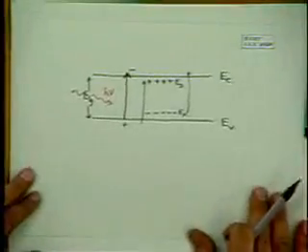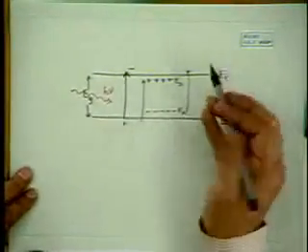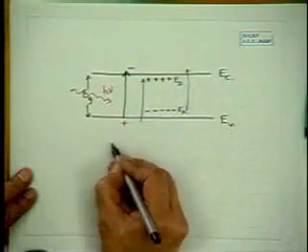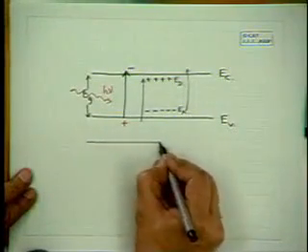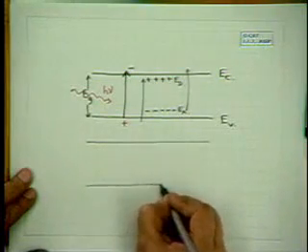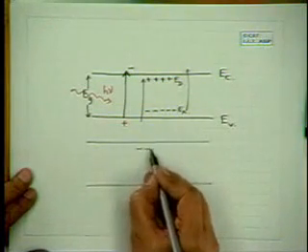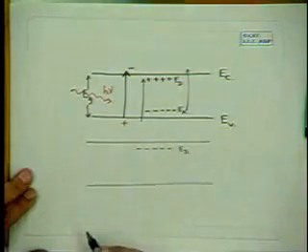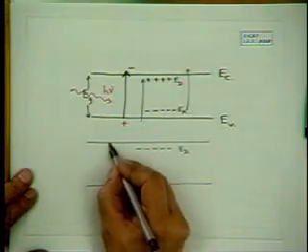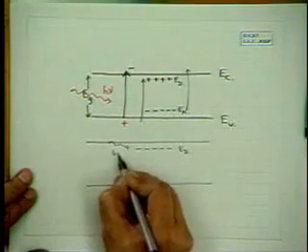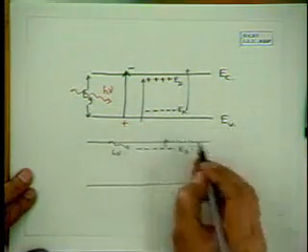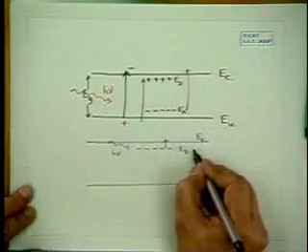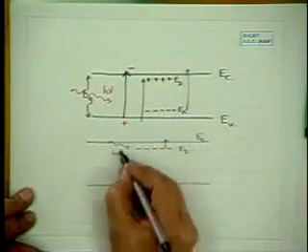Further, at very low temperatures, when the donor levels are filled with electrons, then if the incoming radiation h nu has energy greater than Ec minus Ed, which is typically a few milli-electron volts, one can get absorption.